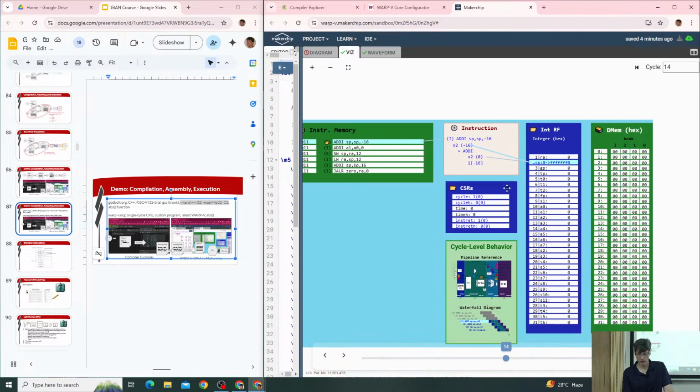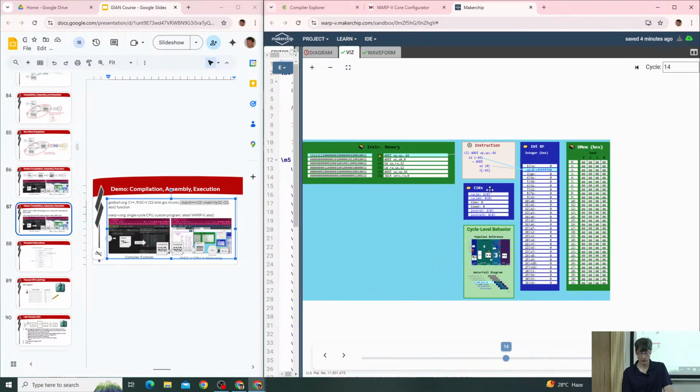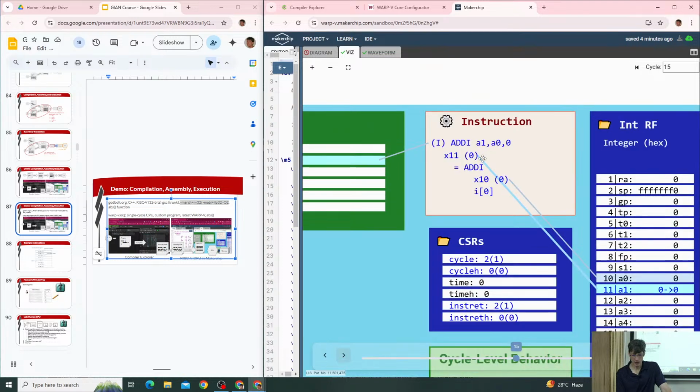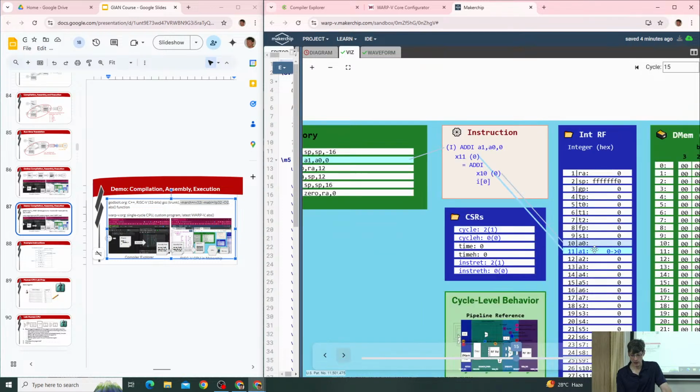So that's the nature of RISC-V instructions, and similar for most instruction set architectures. Very typically up to two source registers, potentially an immediate value from the instruction, and a destination register. And the machine is just going to keep fetching instructions one at a time, performing the operation, and writing back the result into the register file.